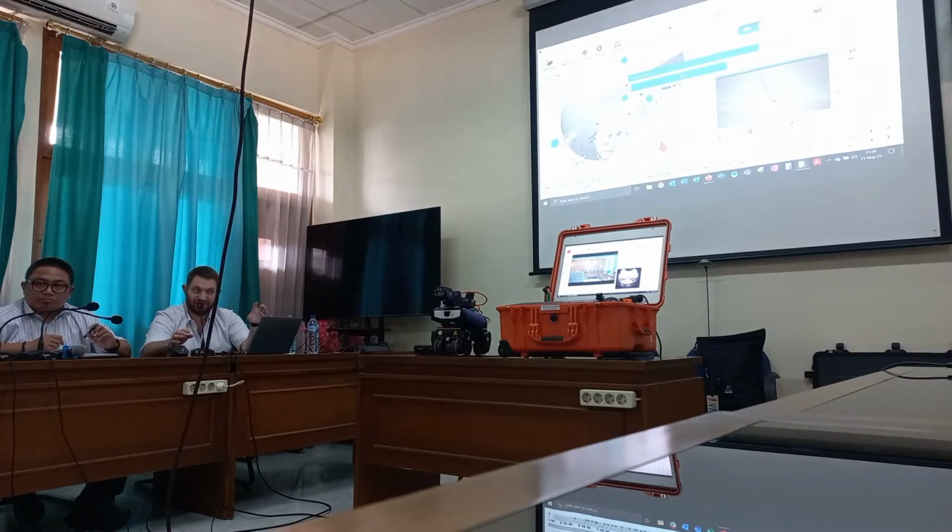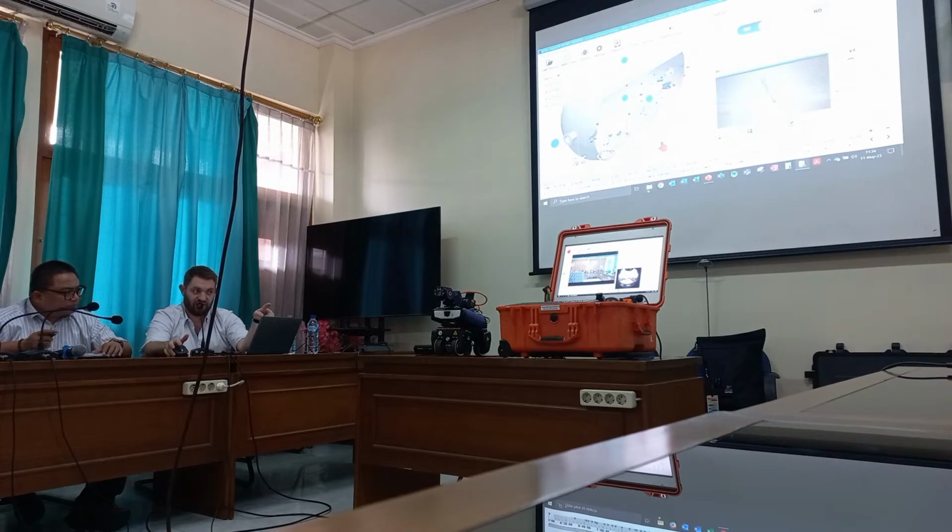This is four-wheel drive or? This is four-wheel drive, yes. 60% to the front wheels, 40% to the back. And then when we push the full throttle, it will send 50% to the back, and if the front wheels start to slip, it will send a little bit more power to the back to push it up over things. And there's some really clever smarts in the way the technology works with the four-wheel drive system.